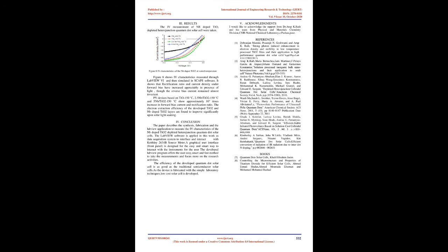upon solar light soaking. In conclusion, the paper describes the synthesis, fabrication, and the LabVIEW application to measure the I-V characteristics of the Nb-doped TiO2 depleted heterojunction quantum dot solar cells. The LabVIEW software is applied in this work as a data acquisition system to interface and interact with the Keithley 2634B source meter. A graphical user interface, the front panel, is designed for an easy and smart way for the user to interact with the instruments. The developed LabVIEW program offers the user an easy, smart, and fast method to take the measurements and focus more on the research activities.